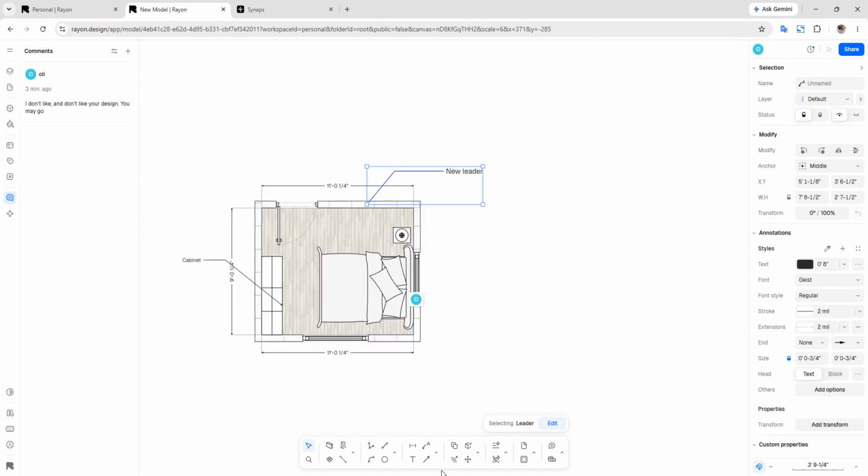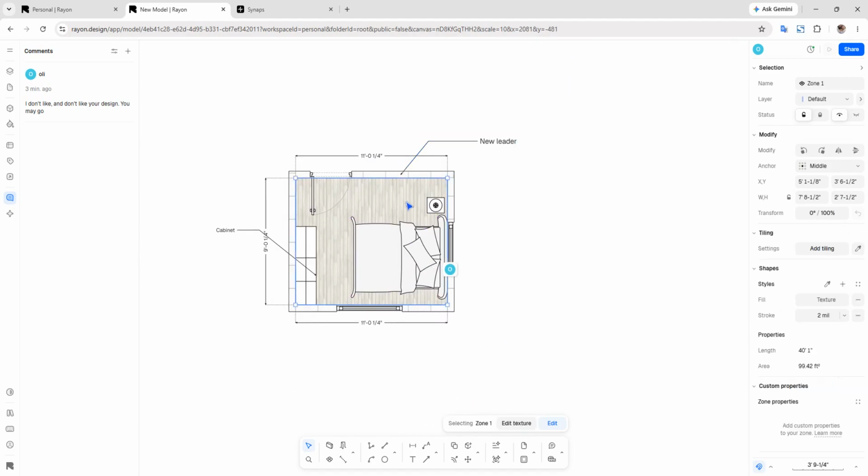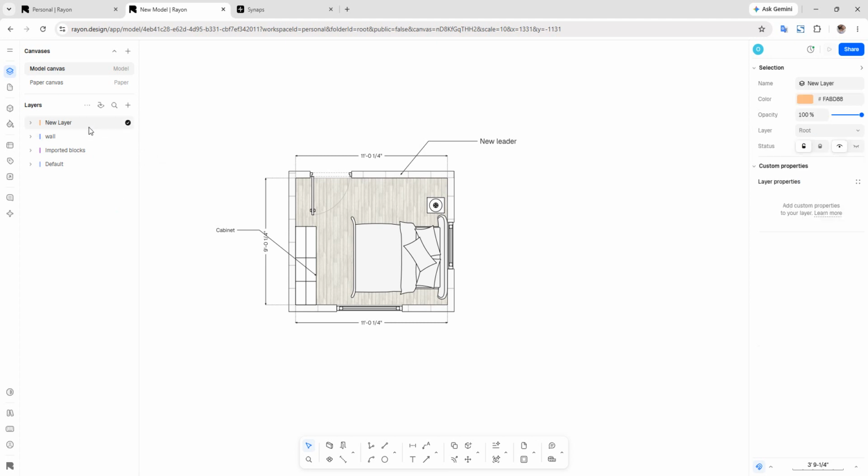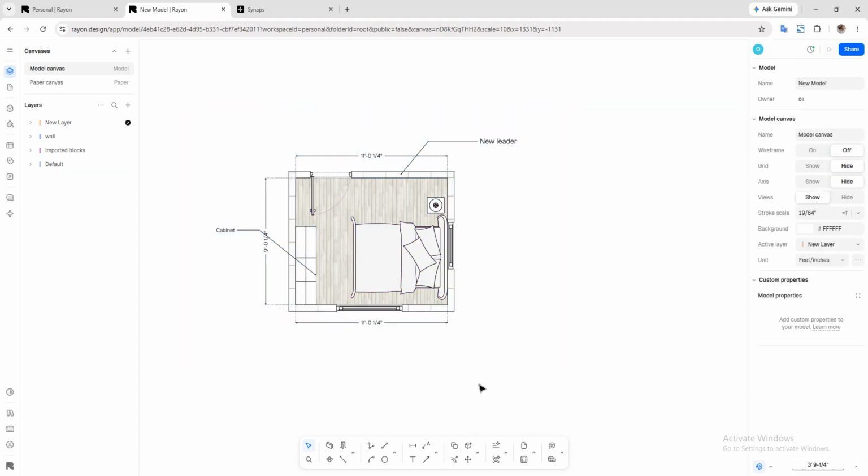What else can we show? Oh, we have the layers. We didn't say anything about the layers. So go for layers and create one by clicking this. Name the layer wall and name the layer column, something like that. Do it as you like, and you can lock the layer, rename the layer, or duplicate the layer. These are very handy if we are going for a complex drawing.